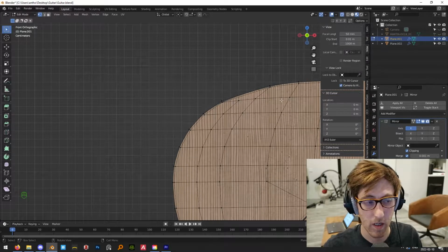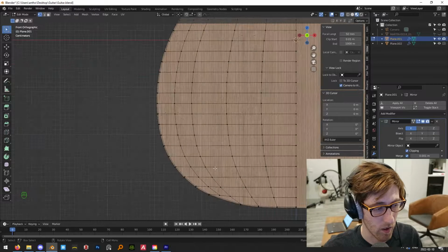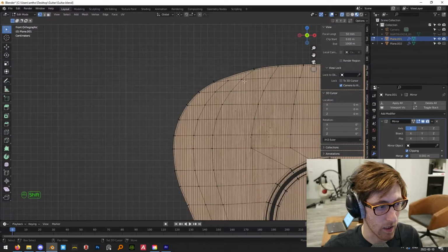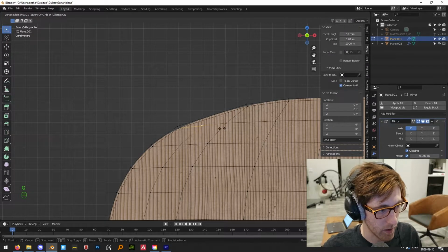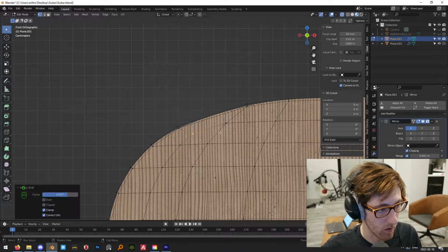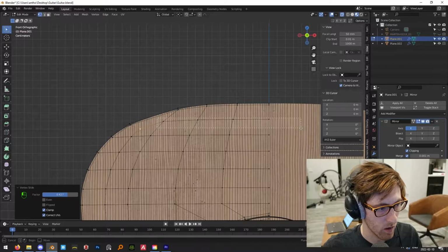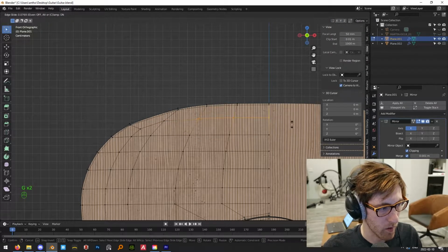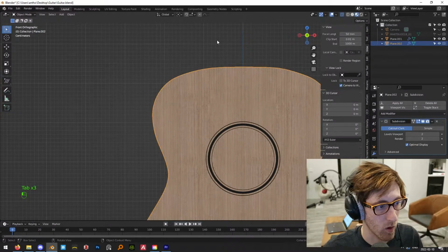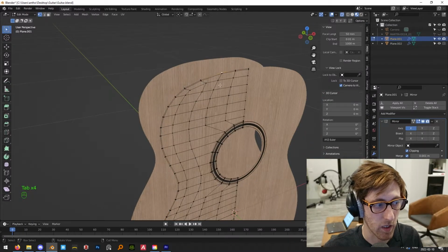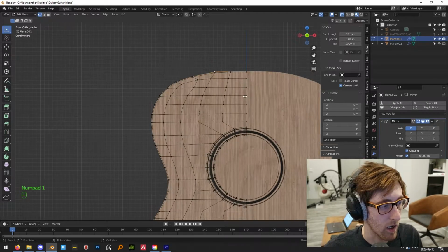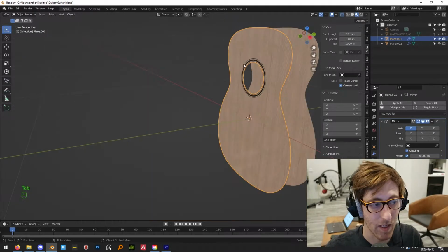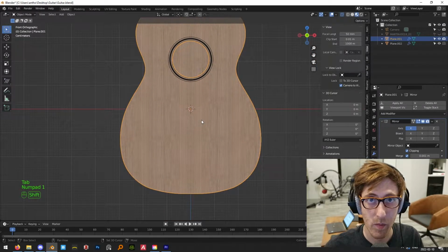And then here, so I added a loop cut here on the right, so that's turned this tri up here and this tri down here on the bottom into quads, and then I'm just going to shape this a little more carefully by GG to drag this vert down, and GG to drag some of these up. Essentially what we're doing here is creating a topology which gives us another edge flow around the outside here. And that's just a little bit cleaner. And so I'll make this correction on the back as well.